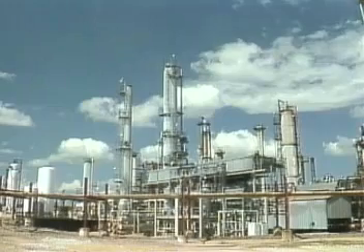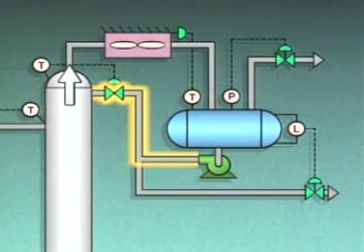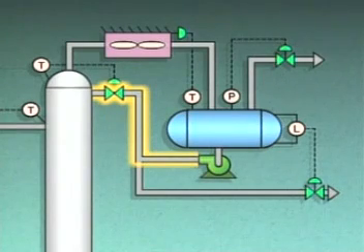Changes in the external reflux that flows to a distillation tower can affect the composition of the tower's products. When external reflux enters the tower, its lightest portion vaporizes and flows out of the tower with the other overhead vapors. The rest of the external reflux flows down the tower. The reflux helps to condense the heavier components of the vapors in the tower.